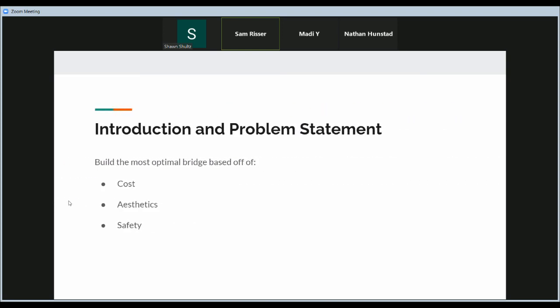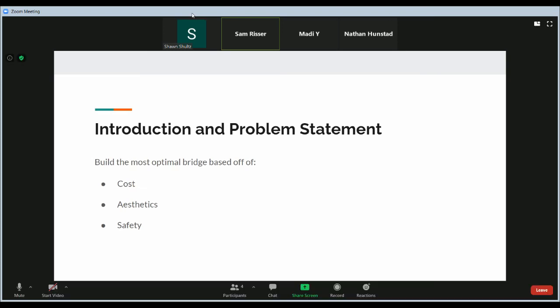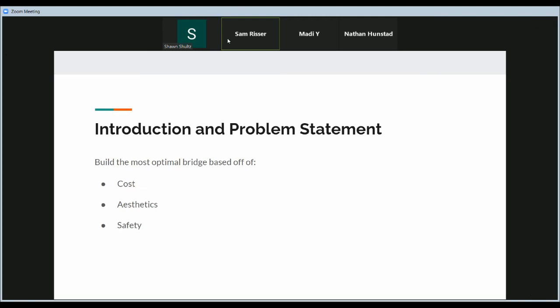Our objective was to build the most cost-effective, aesthetically pleasing, and safest bridge design possible using the West Point Bridge Designer software, basing off of the 8 truss designs we were given. The starting conditions for the 32-meter bridge span were a deck elevation of 12 meters, standard abutments, no pier, 1 cable anchorage, high-strength concrete, 0.15 meters thick, standard 225 kilonewton truck that was 2 lanes.